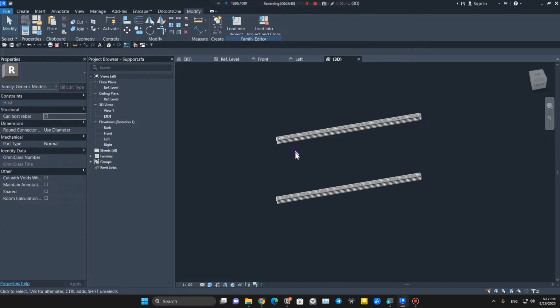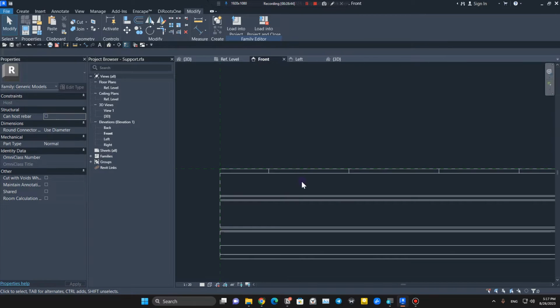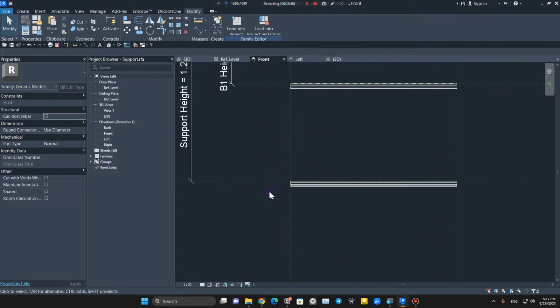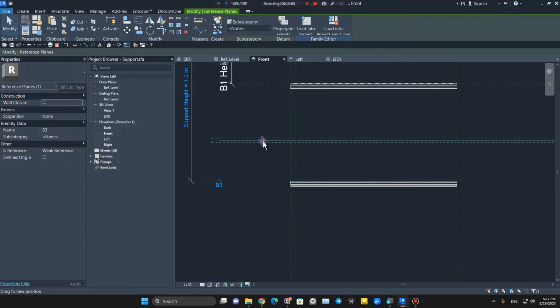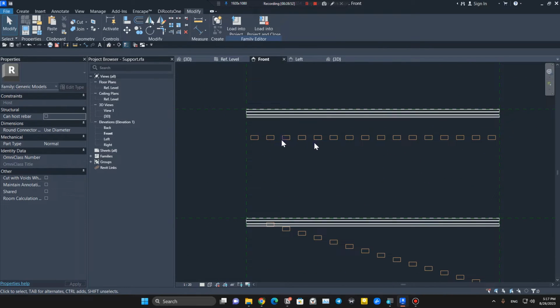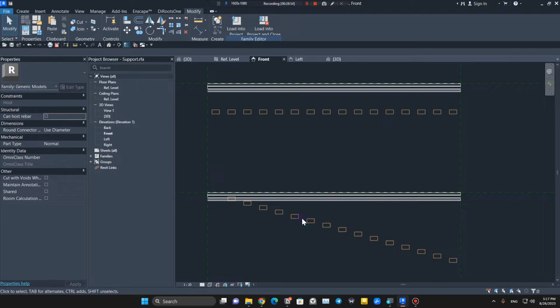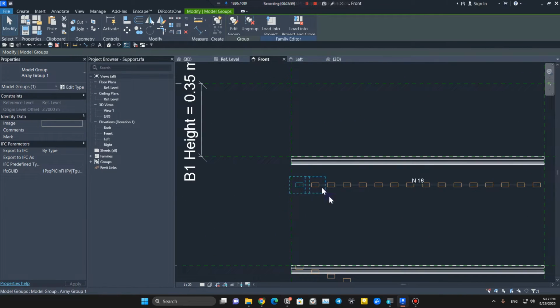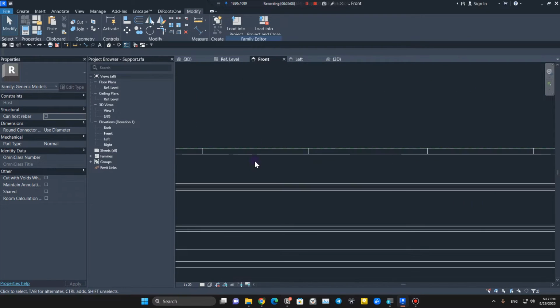But before adding the vertical parts, let's see if the voids are going to work in different heights. For example, on this side, you can see these voids are working, but this one isn't. So it's not working for these ones too. So we have to do something here. Press Ctrl Z, and for this one,